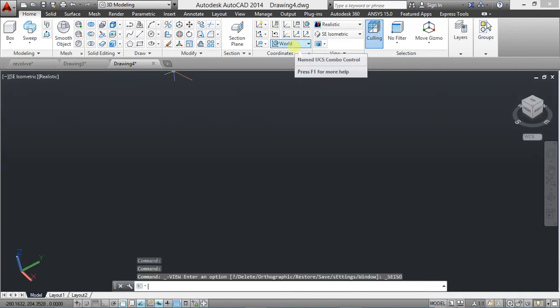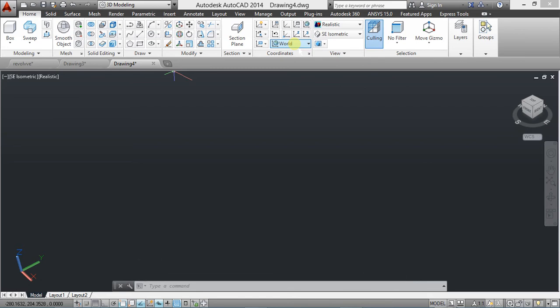Okay, now choose the side to be isometric. We are going to sketch this on right. Okay, when you are sweeping, sweeping has two properties. You must have a sketch and you must have a path. That is a sketch which is the profile, and a path which that profile will be swept along. Now take it from right.